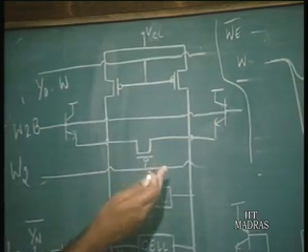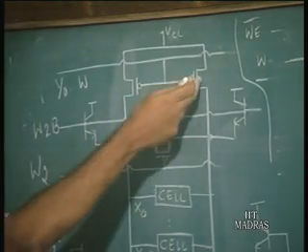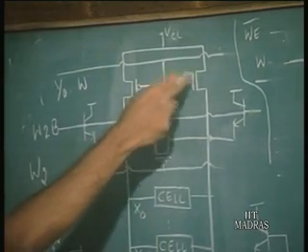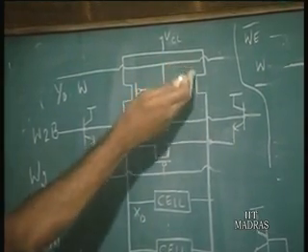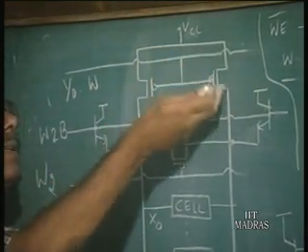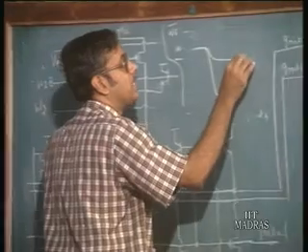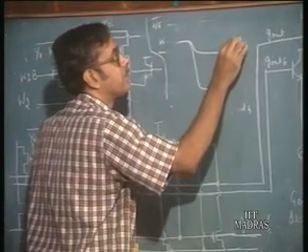And then finally, this output voltage is going to rise slowly, because now after the write cycle these PMOS transistors turn on, and then both the line voltages are pulled slowly towards VCC. So, they move like this.